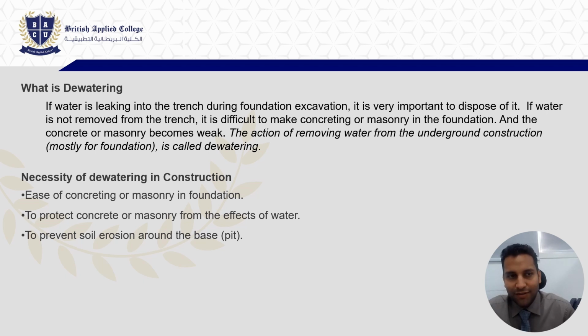Dewatering. If water is leaking into the trench during the foundation excavation, it is very important to dispose of it. If water is not removed from the trench, it is difficult to do concreting, right? So we do the dewatering process. Dewatering is really important. If you don't do dewatering, the ground is not stable. There would be leakage of water everywhere while you are making the foundation, which will lead to many drawbacks.